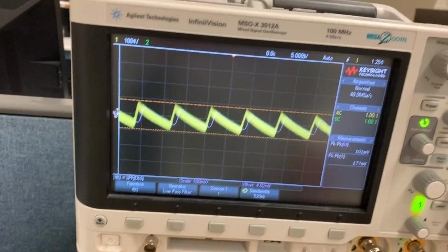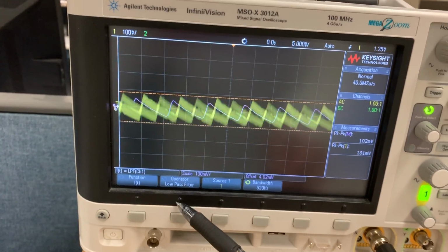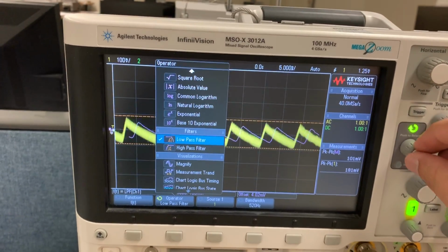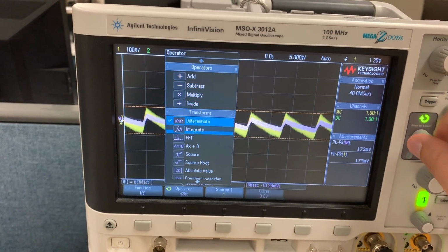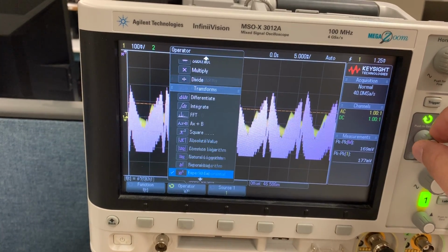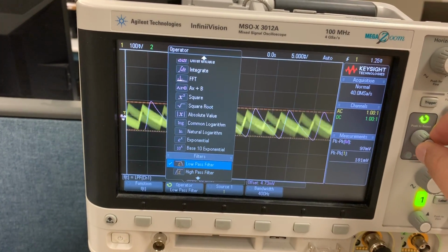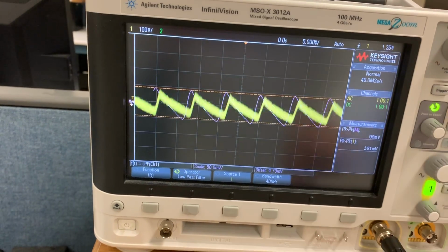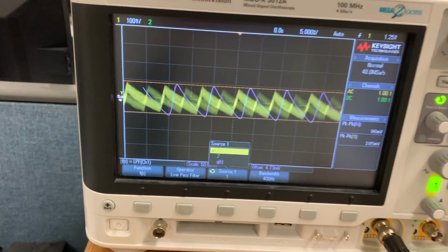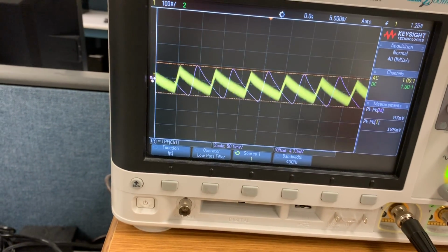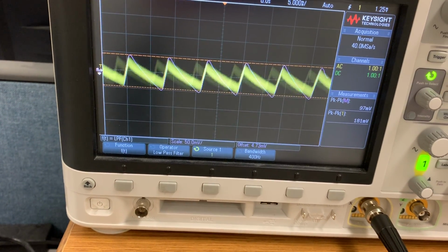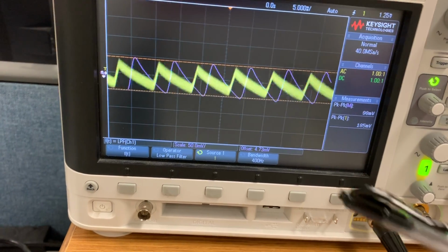If you look at this guy right here, the operator low pass filter. When you do math, as we have done FFT before, what you have done so far is go up and down and pick the FFT. Right now what I'm suggesting is we go in the filter section and select a low pass filter, select the source as our channel one, because that's our input channel. That's what we are measuring. And now we want to see what the filtered out waveform should look like.